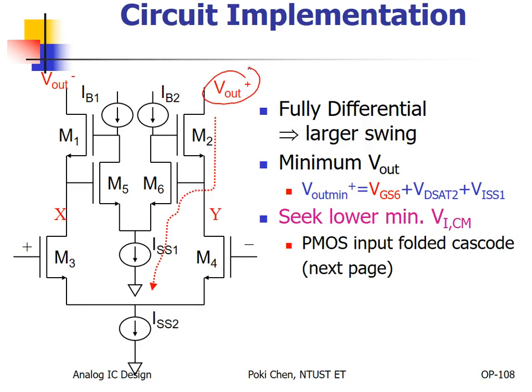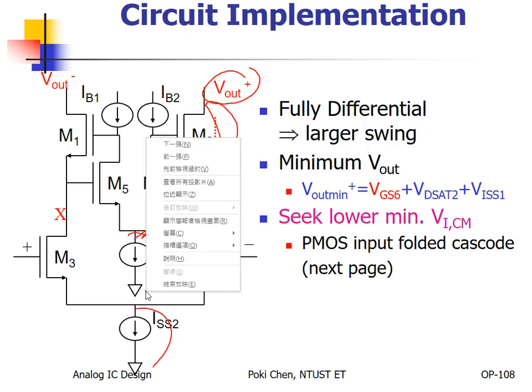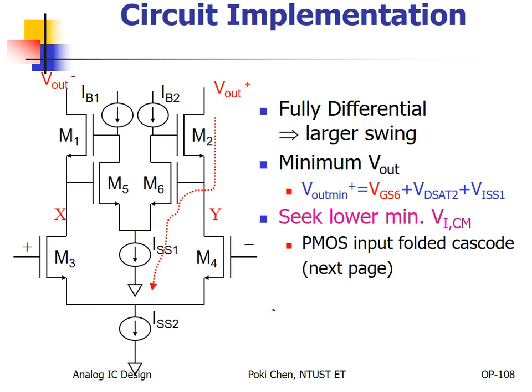Maybe you will say, hey, it's delta V, delta V, delta V. Yeah, that is one possibility, but that is only one requirement. But how about the other requirement? If we go to the other route, you have delta V here, but one VT, one delta V, and the other delta V. What does it mean? For the first route, you only need 3 delta V, right? But for the second route, the minimum should be 1 VT plus 3 delta V.